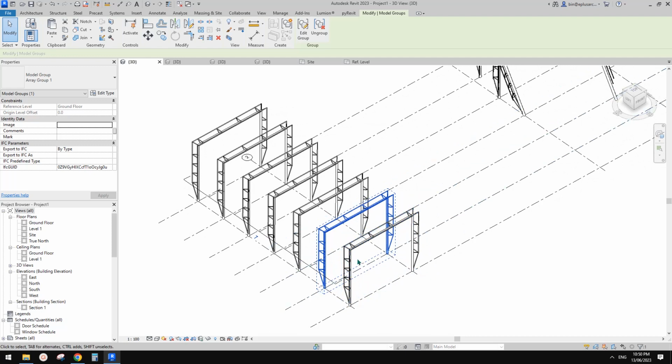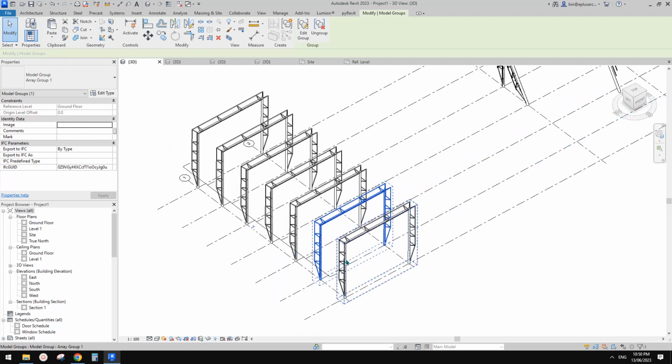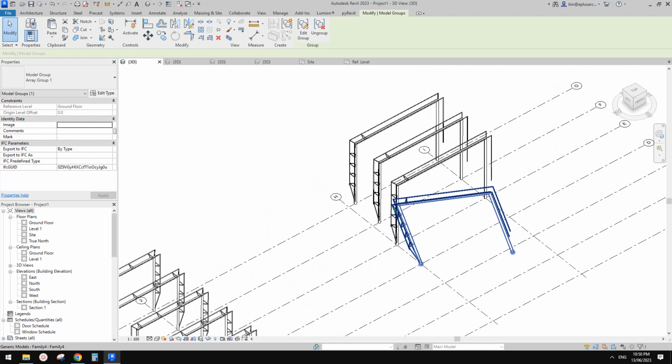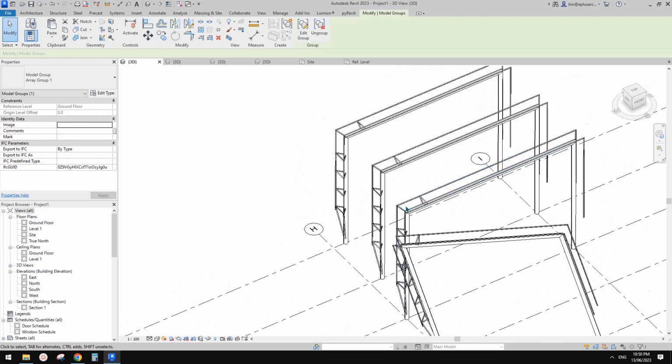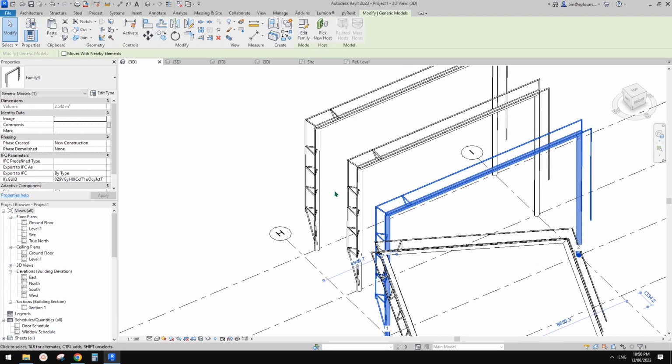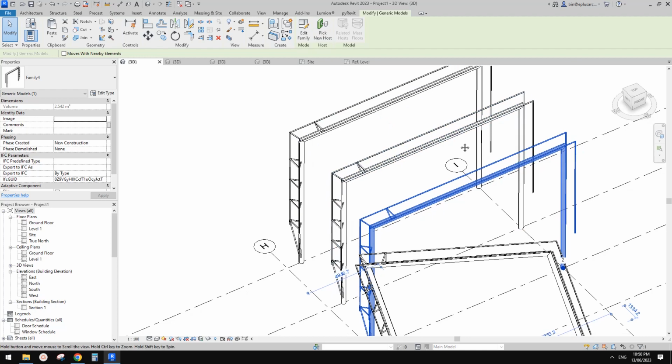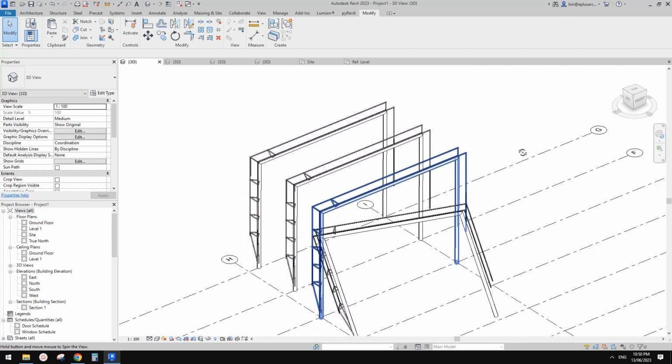You need to constrain the arrays, and you need to create a lot of reference planes maybe. But for adaptive family, there's a lot of snapping onto something, and snapping onto a percentage of the edge, so it's quite simple, right?